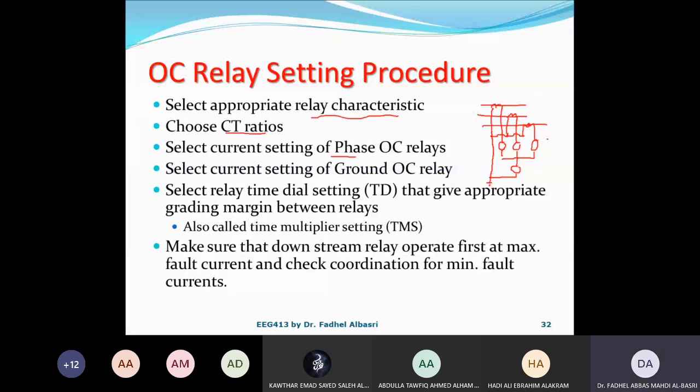So when we look at this as a 51 relay, here we can have 50 and 51. Now we have to have a time setting, and time dial setting. The pickup setting, I pickup setting, and time dial setting. I say I pickup setting, or sometimes I make it as I setting.